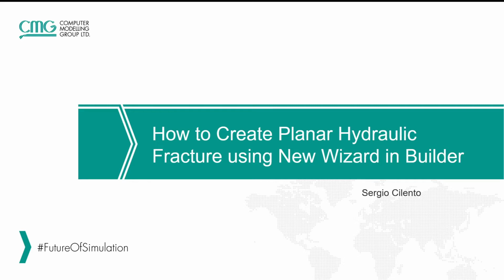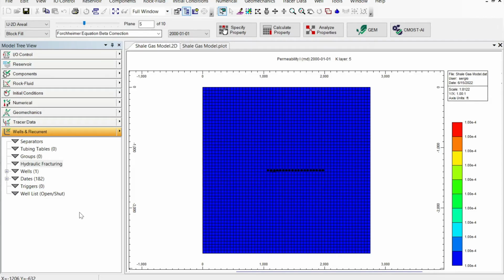In this exercise, we are going to start from an already created model for shale gas, where we are going to create 4 vertical planar fractures in the horizontal section of the well. Here we can see the model. The model has a very low permeability, around 1e-4 millidarcy.